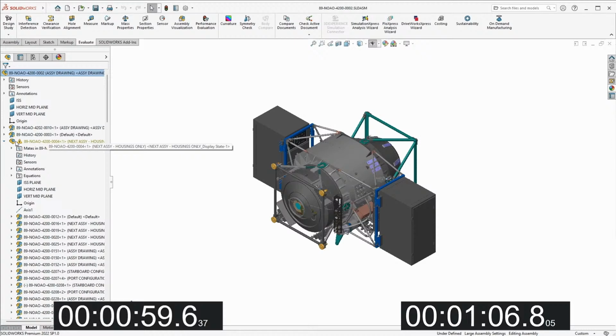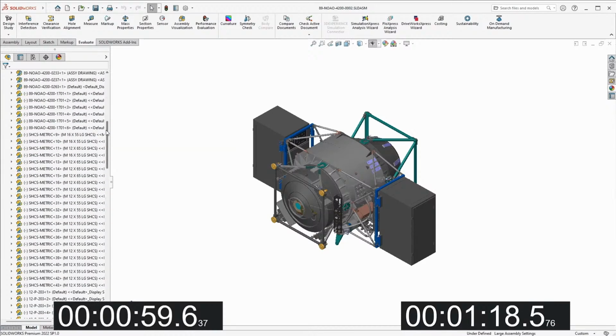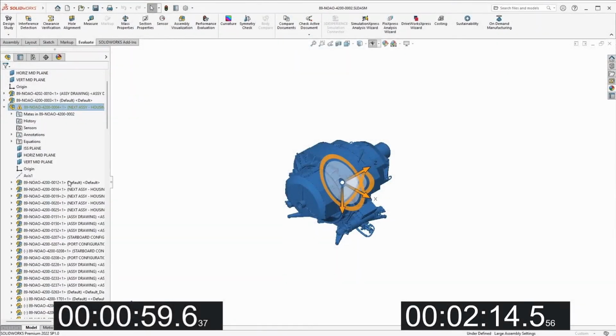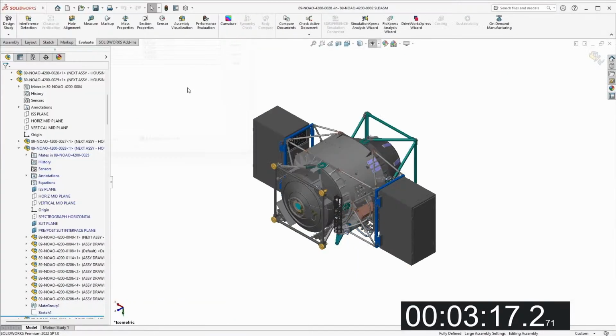However, that error is not in the top level subassembly. So now we have to fully resolve this to find out exactly which component or subassembly it has to do with. So we have to go ahead and resolve this full subassembly here. So now we can find out which part it is and go in and update that and return to the context of the main assembly. But it took around 3½ minutes, which is even longer than if you fully resolved, opened it, and made that